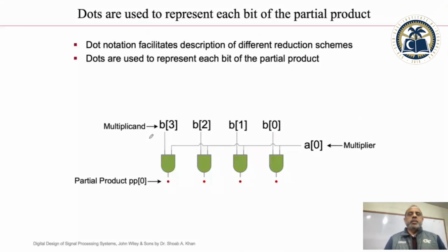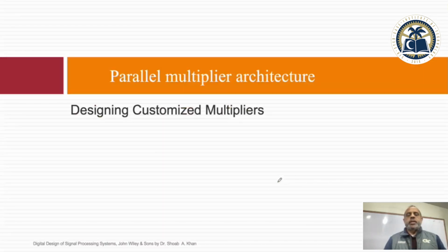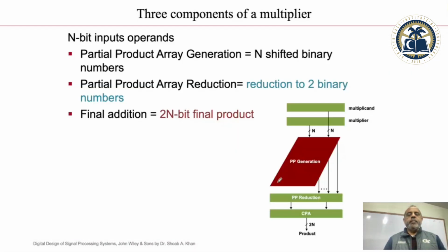Same is the case if you think about a multiplier. A multiplier does nothing but add all the partial products together. So once you are generating partial products of two numbers, let's say you are multiplying b with a 4-bit a, you take the 0th bit of a and AND it with all the bits to generate one layer of partial products. Okay, so here are the partial products.